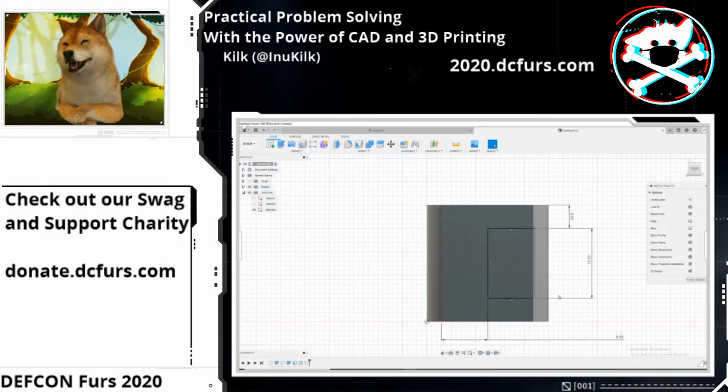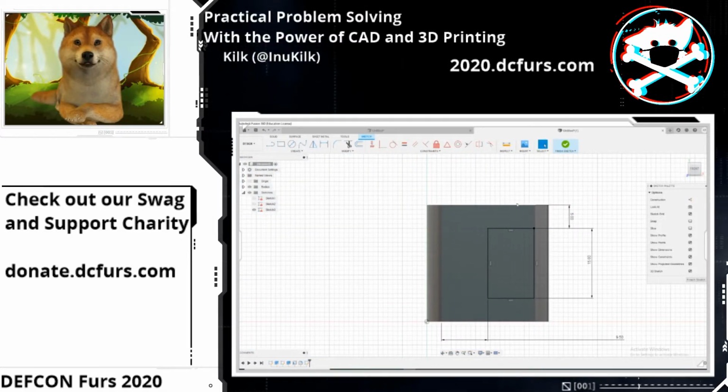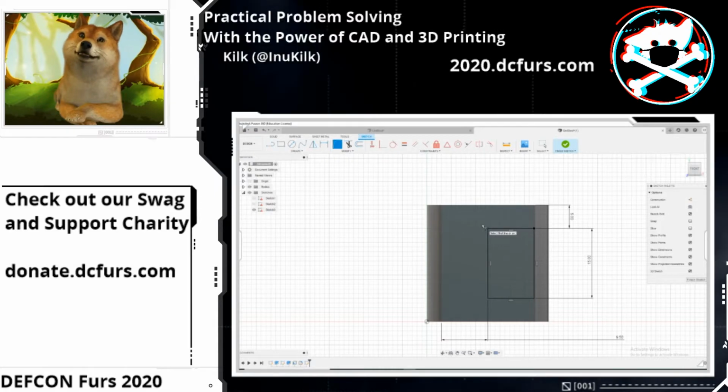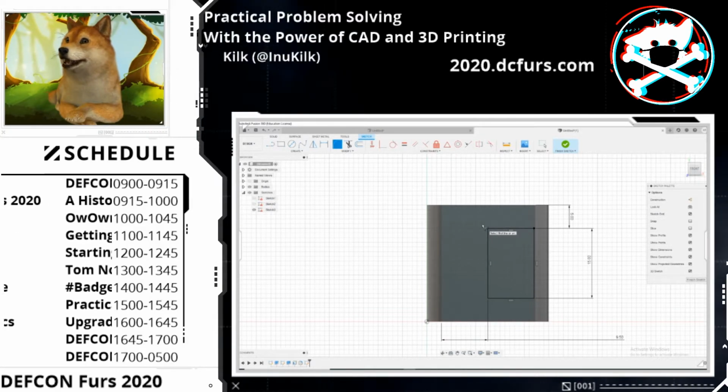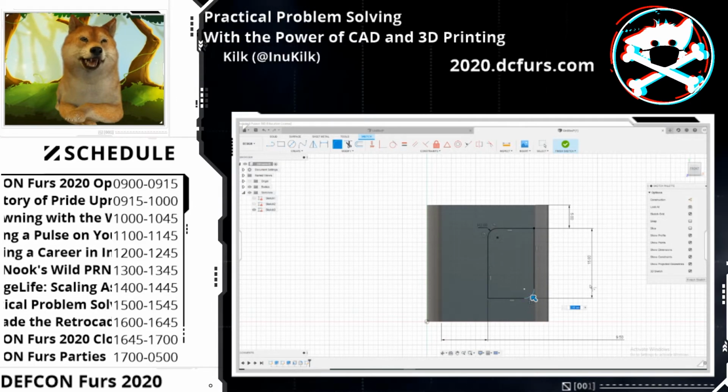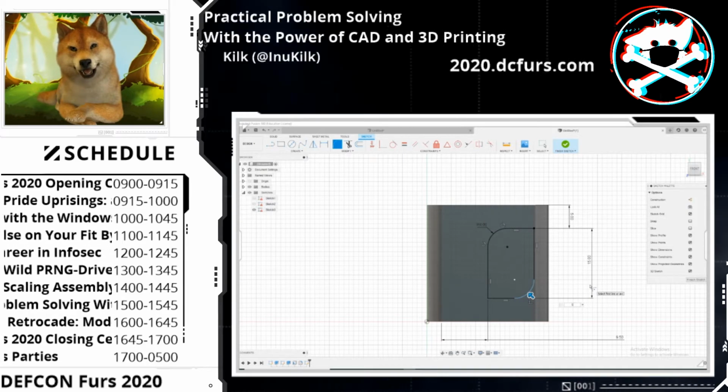We're going to double click this, and then we're going to add a fillet to the sketch. Instead of doing it when it's a 3D object, we're going to do it when it's 2D. And usually this is better to do, in my opinion. But actually, no. Scratch that. Usually it's not a good practice to do it in a sketch because you don't have control over it. You can't go back and edit it. You'd have to go into the sketch and manually edit it, which is a pain, whatever you prefer. So let's hit this one, let's hit this one, and let's make it 4, 5, maybe 6.